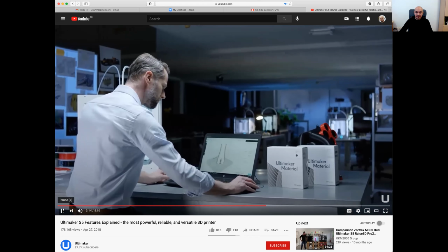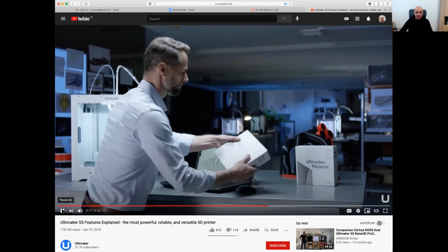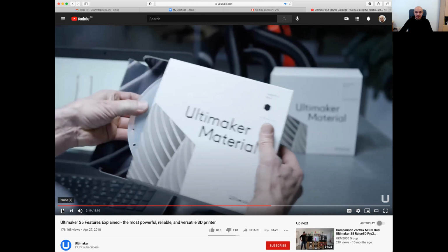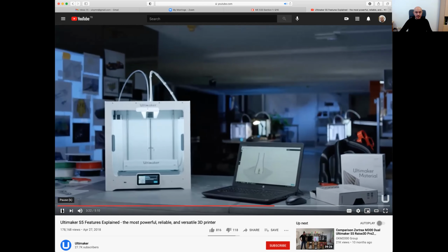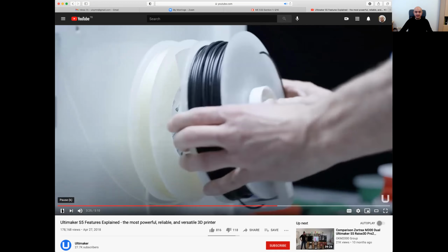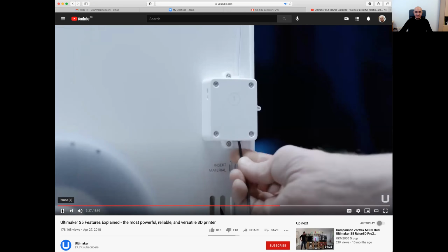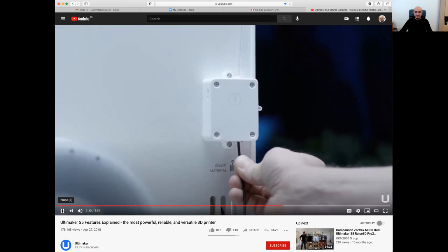The Ultimaker S5 comes with Tough PLA, a technical material with toughness similar to ABS, but so they have various materials. You don't need to use a single material. They have PLA, PVA, ABS. There are many thermoplastic materials. Some has high toughness values, some has high elastic values. Depending on your application, you can find the proper material and simplicity of PLA. Ideal for rapid prototyping with large prints. Tough PLA is compatible with Ultimaker support materials, including PVA.